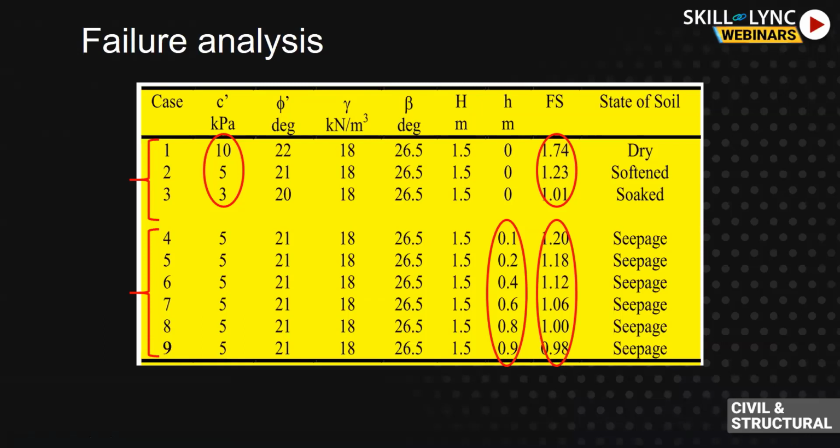Just to give an idea of the soil formation here. At this project site, the soil formation is called Bukit granite, and it's a residual soil. Residual soils are the original soils below ground, which are formed over millions of years by weathering of the rock. And this particular Bukit granite formation has a lot of clay, actually a lot of kaolin material.